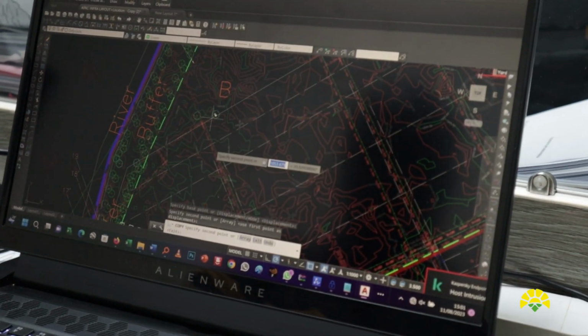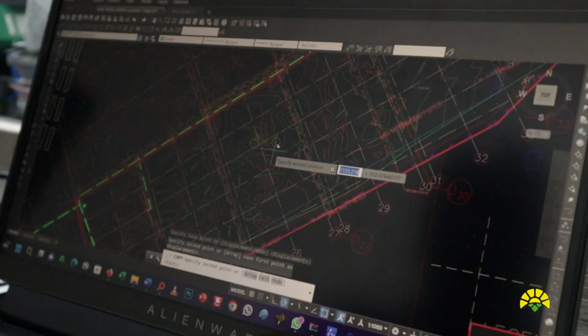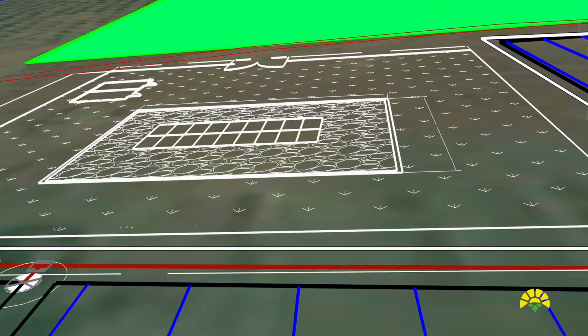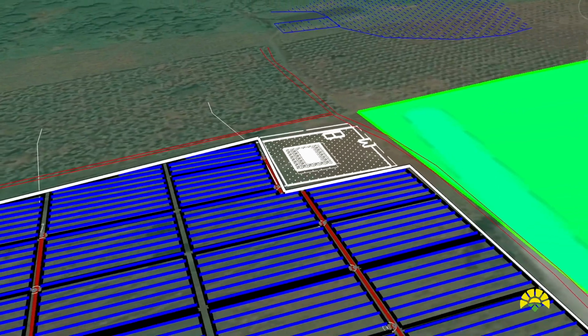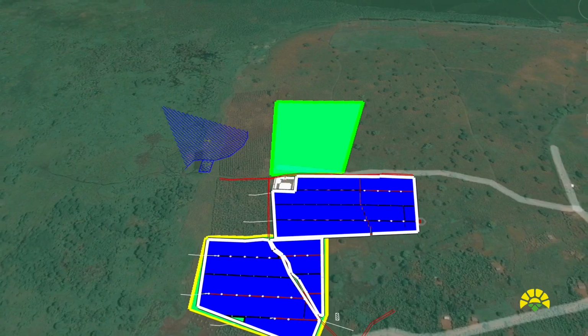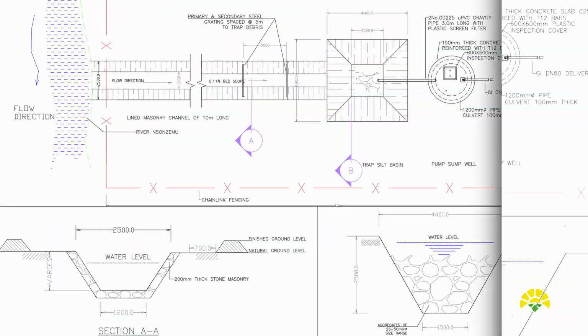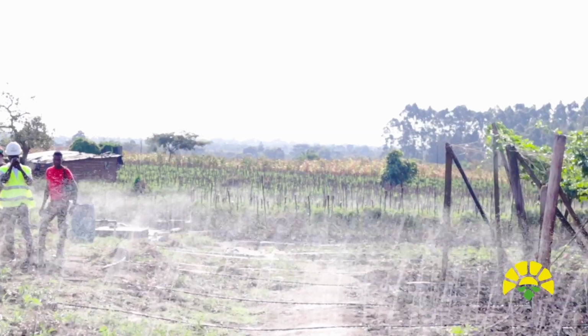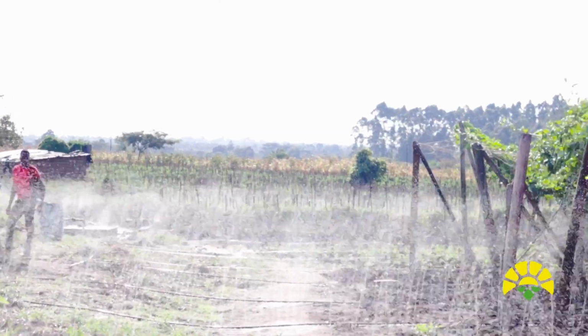The water supply system consists of an intake, which is a borehole as a source, and then we have a pump house, which houses wellhead fittings and different electromechanical components. Then we have a transmission main that delivers water to the reservoir. Then from the reservoir, the water is distributed to the target areas by gravity.